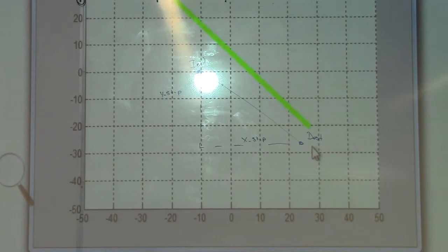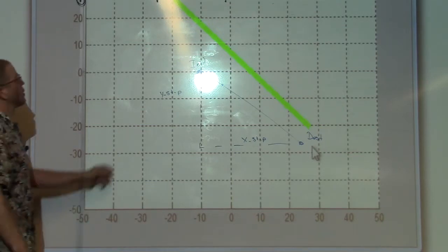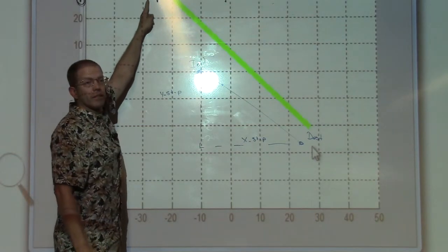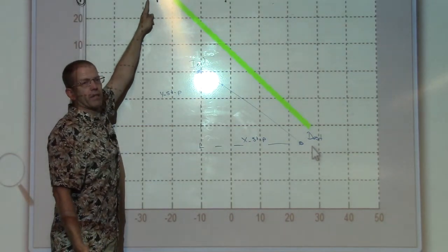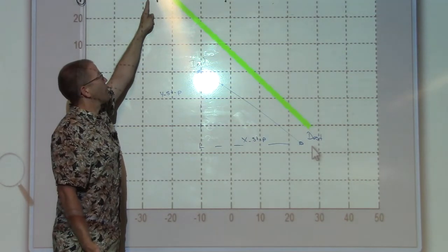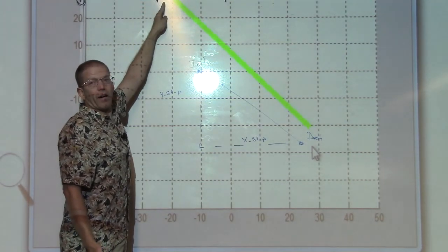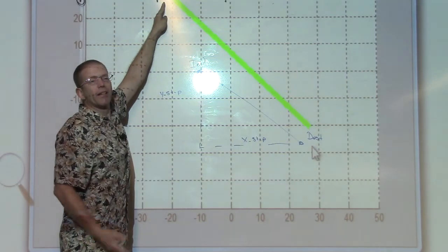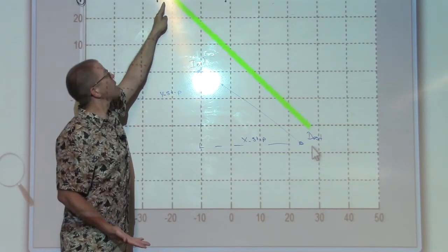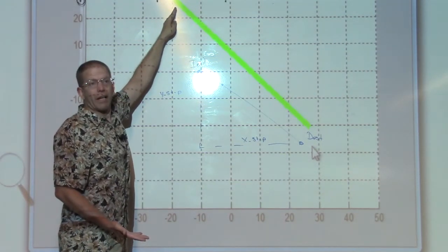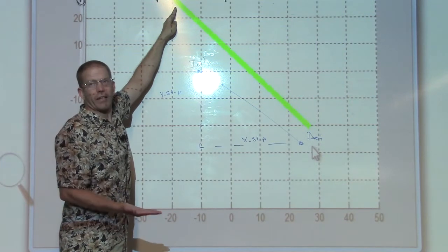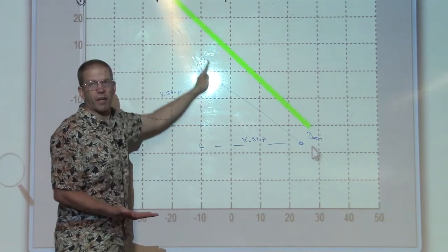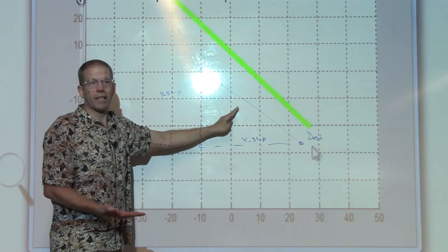We're just going to put that end effector on the line and slide everything else. That's exactly it. We need to calculate the initial set of joint parameters. Then we go through, increment our end effector location, find the new set of joint parameters, increment the end effector location, find the new set of joint parameters, all the way down.